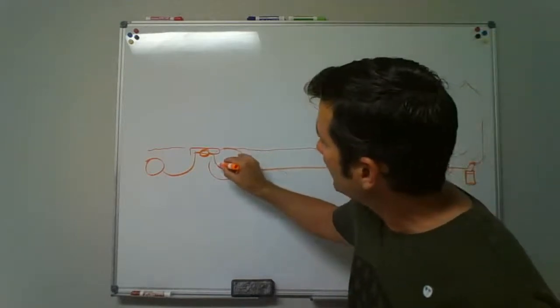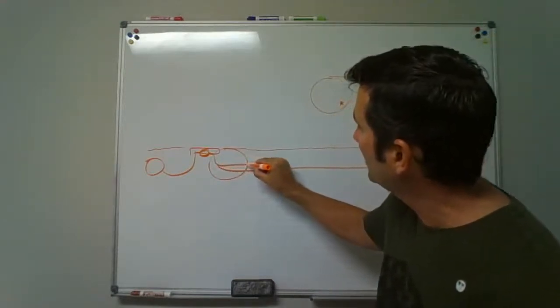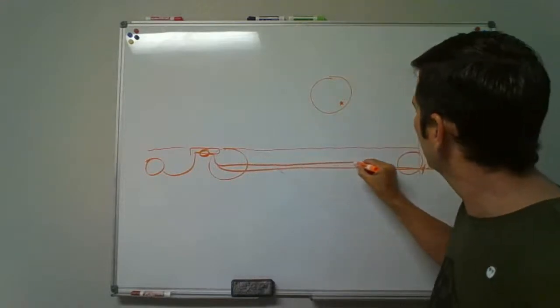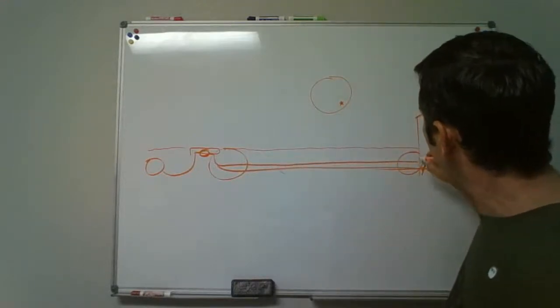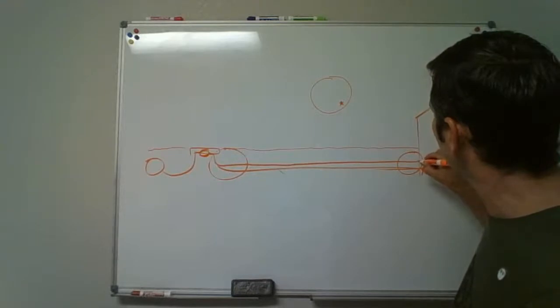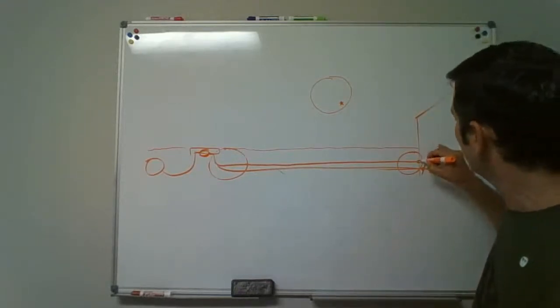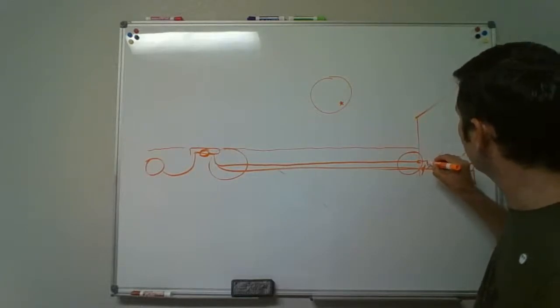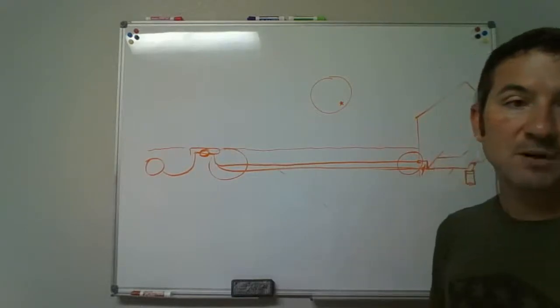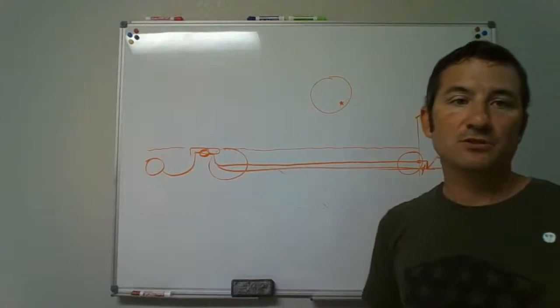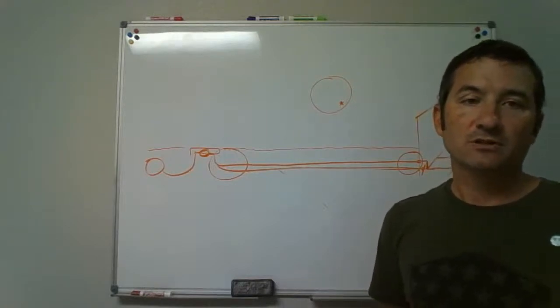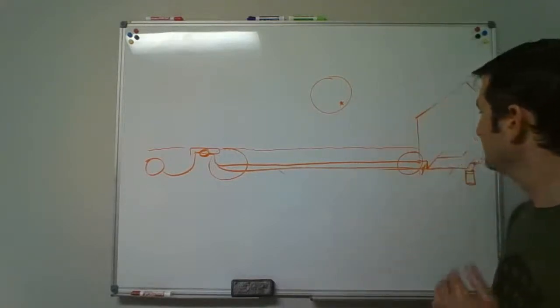And I tied on and ran a new PEX line. I actually knocked a new hole through the wall, put a sleeve in, patched around it, and tied up inside the house with PEX piping. Put in a new house shutoff valve, new pressure reducing valve, make sure all that was good.